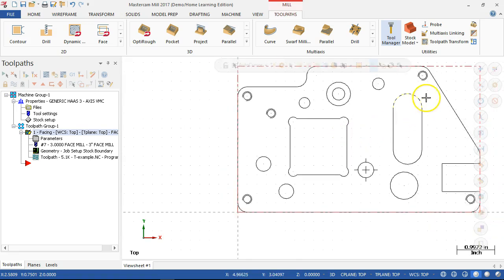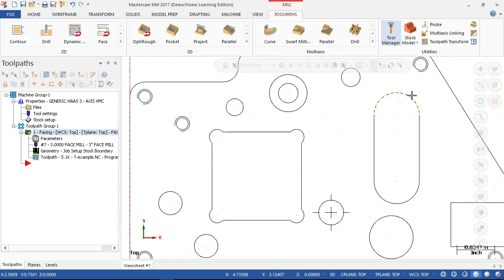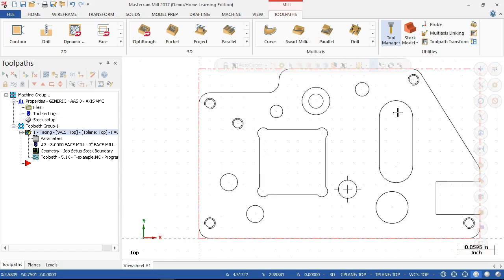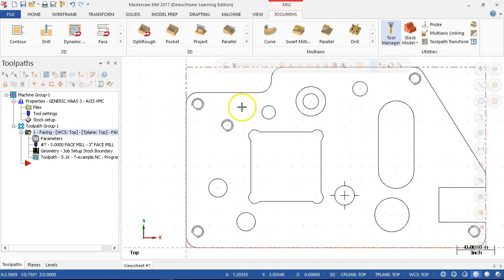The slot, we'll try the slot operation since it kind of ramps in a little bit different, but if I don't change tools, then I haven't really gained much. So I think this was about 2 inches wide, and this is an inch or 3/4 inch. That says that if we're going for production, I probably need to drop the 1/2 inch end mill in there first, come back with 1/4 inch, and finish this one with the 1/2 inch. All right, so again, just making decisions as we go.